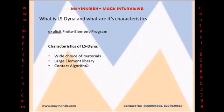Then, the large element library. LS Dyna is a hub for different element formulations. Simple and fast elements for standard applications are available in LS Dyna. Higher order elements are also available but costly. Costly in the sense it will take more time for solving.